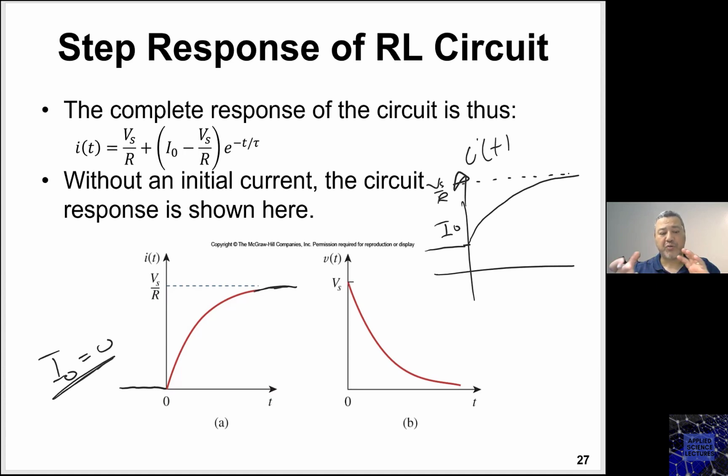How to calculate those values is based on the expression that we have introduced, either for the voltage for the capacitor being charged or discharged, or the current in the inductor being charged or discharged. So you need always to keep in mind that for the source free RC or RL circuits, what you need is the initial voltage for the capacitor for RC circuit, right? And the tau. For source free RL circuit, what you need is the initial current for the inductor and then tau.